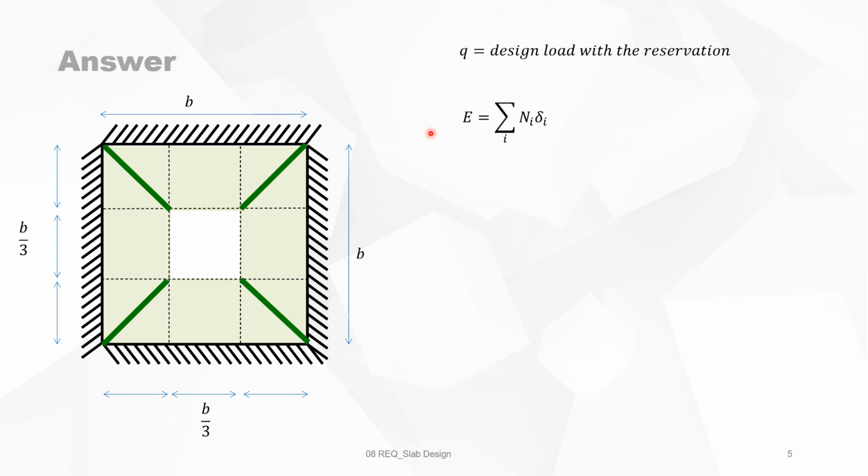We calculate first the work done by the external forces. First we take the rectangular sections. So for the rectangular section it is B/3 times B/3 multiplied by the mean deflection. This portion is the deflection of delta. So the mean deflection of a rectangle is then delta/2. And this is this term because we got 4 rectangular portions of the slab.